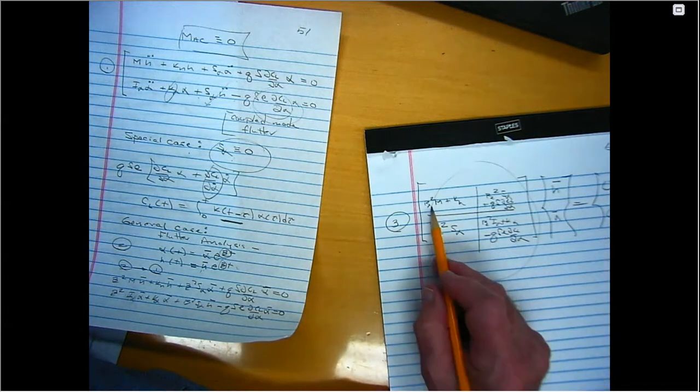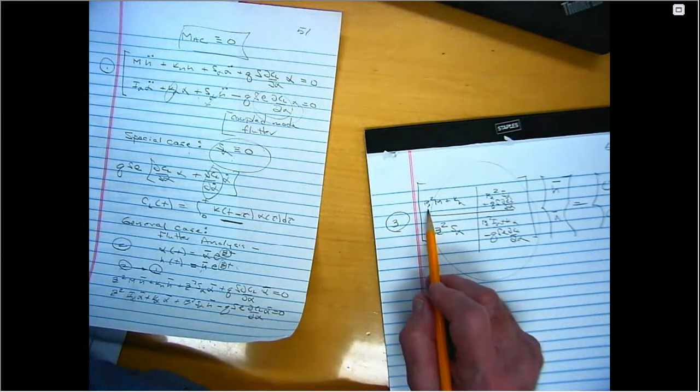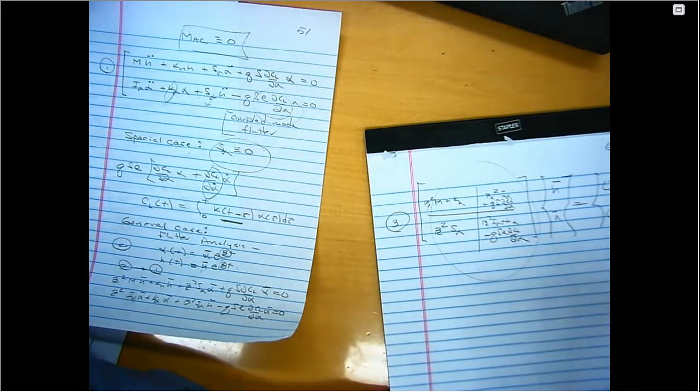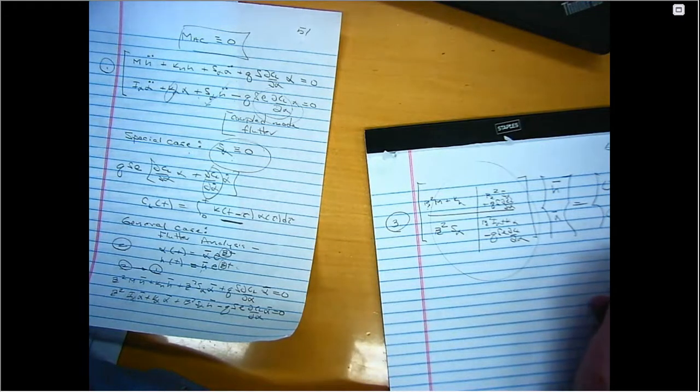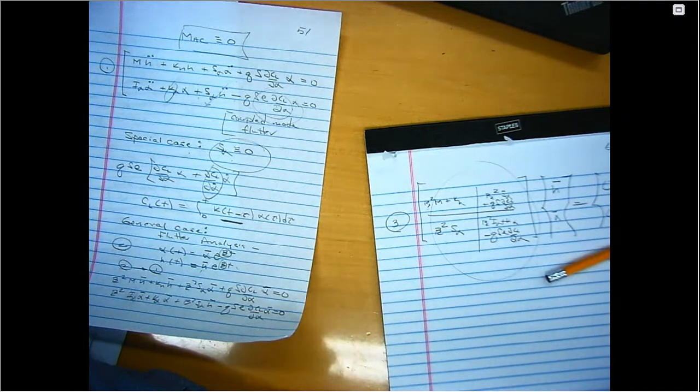It will be a quartic in beta because I've got beta squared times a beta squared here. But the good news is, because of my simplifying assumption about the aerodynamics, it's only a quadratic in beta squared. So I can use the quadratic formula to find beta squared, and then if I take a square root, I can find the beta. So there are 2 beta squareds, there's 4 betas.